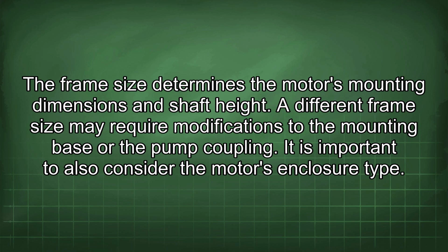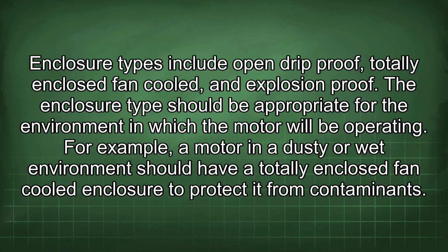It is important to also consider the motor's enclosure type. Enclosure types include open drip proof, totally enclosed fan cooled, and explosion proof. The enclosure type should be appropriate for the environment in which the motor will be operating. For example, a motor in a dusty or wet environment should have a totally enclosed fan-cooled enclosure to protect it